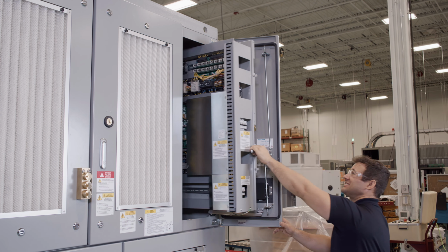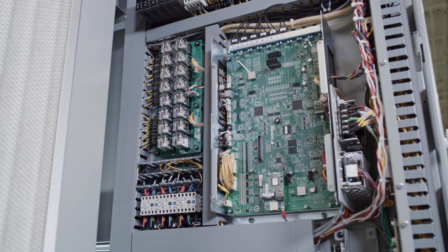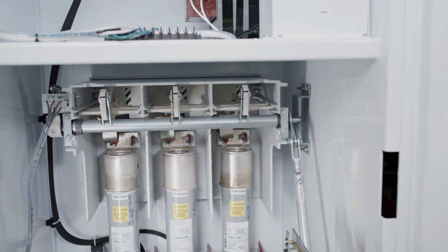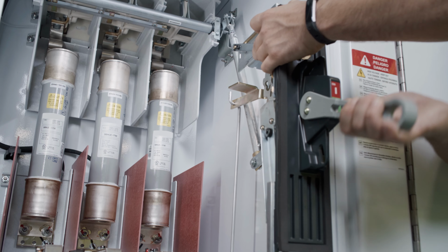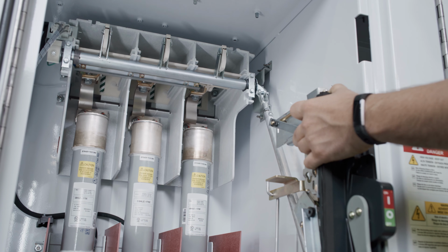A low-voltage control section provides an interface for control inputs and monitoring, and units may also be provided with optional switchgear to provide an integral means of disconnecting the medium voltage supply from the drive components. In this session, we have introduced the basic construction of a multi-level medium voltage drive and explored how multi-level topology benefits power quality, both on the supply and at the motor.